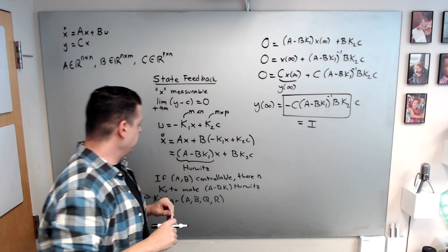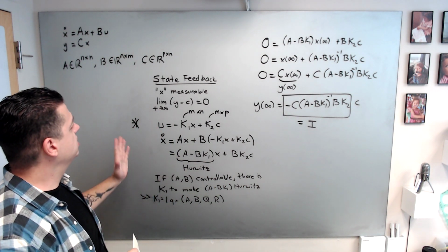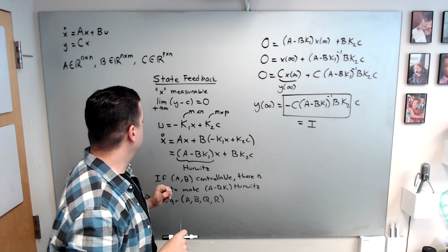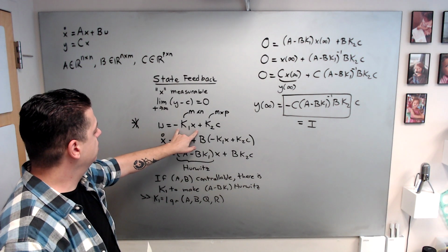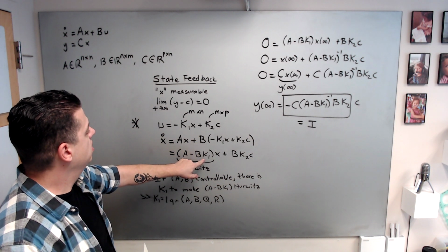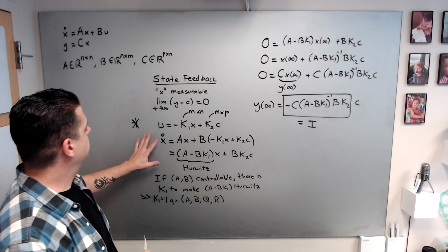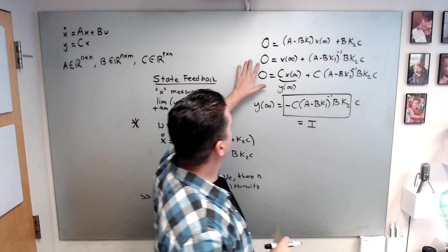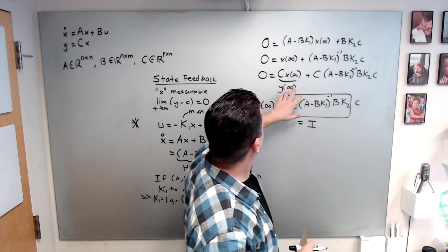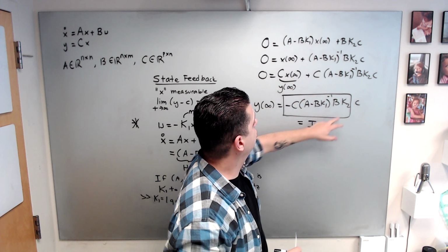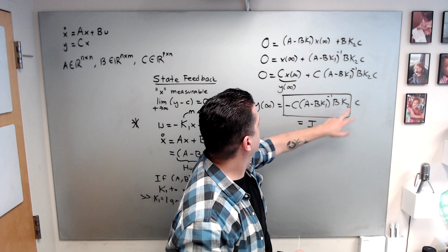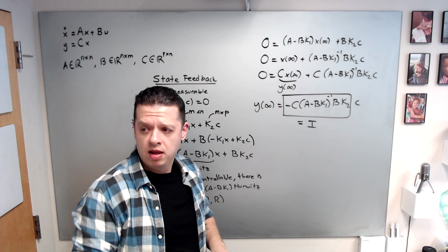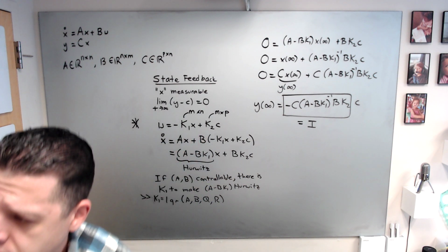All right, so basically, this is state feedback with this specific control structure, feedforward feedback. First choose K1 to make this Hurwitz. Since the command is constant, x will converge to an equilibrium point. Then we are characterizing this equilibrium point. Then from here we are finding y infinity, and then we choose K2 to make this identity. This was the first controller type that I want to talk about.